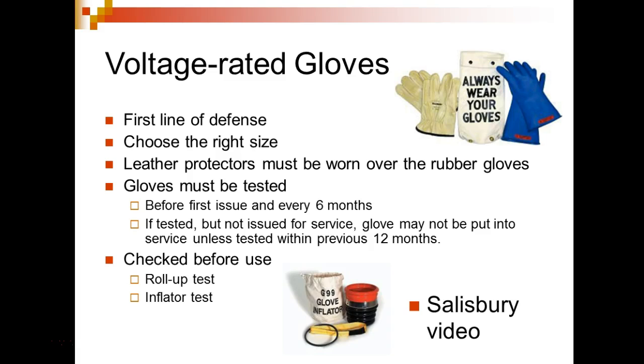What we're trying to do is get you in the habit of looking at this. Before first use, test every 6 months. Gloves tested but not issued for service may not be put into service unless tested within the previous 12 months.